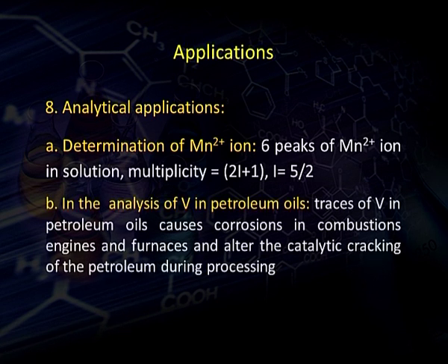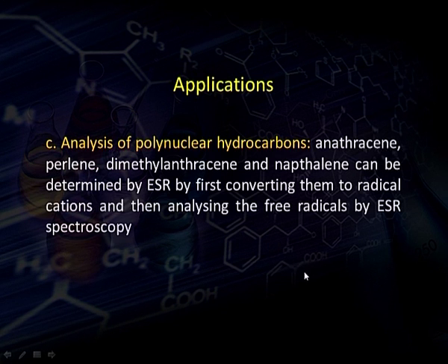Second, in the analysis of vanadium in petroleum oils. Traces of vanadium in petroleum oils cause corrosion in combustion engines and furnaces and alter the catalytic cracking of the petroleum during processing. So, with the help of ESR technique, we can find out whether vanadium is present in the oil or not. Next, we have analysis of polynuclear hydrocarbons. Polynuclear hydrocarbons like anthracene, perylene, dimethylanthracene and naphthalene can be determined by ESR by first converting them to radical cations and then analyzing the free radicals by ESR spectroscopy.